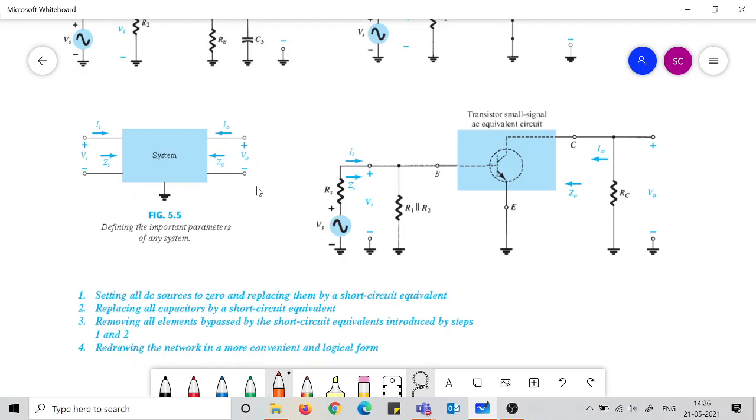That is the meaning of V0 coming out to be negative. I0 may come out to be positive or negative. If I0 comes out to be negative, it only means that the direction of current is in the opposite direction. But as per definition, our impedances will be positive, and you will also find in calculation that impedances will come out to be positive if we maintain this sort of a definition.